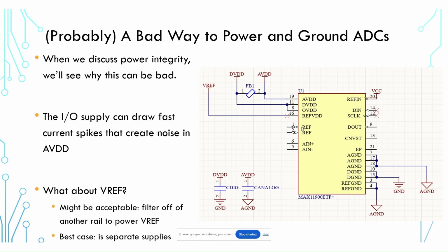It's not continuously adjusting in order to read that input voltage. And so, in that case, it's essentially just reading DC at all times. All you need to do is ensure that all your analog stuff is operating at DC. So that's one instance. Again, I would advise checking it either through simulation or, much easier, through test before you just start placing ferrite beads between all your digital supplies and your analog supplies.